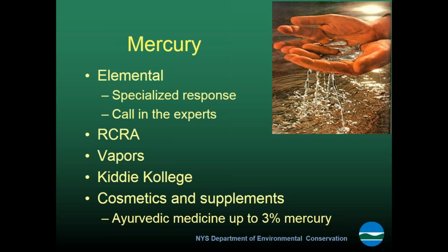There's two levels of land disposal restrictions for mercury-contaminated material: high merc and low merc. If it's high merc, you actually have to get it retorted, get the mercury out of that, and that mercury that's then extracted is actually stockpiled at a facility. It's not disposed of. They want to get this mercury out of the environment permanently and completely.